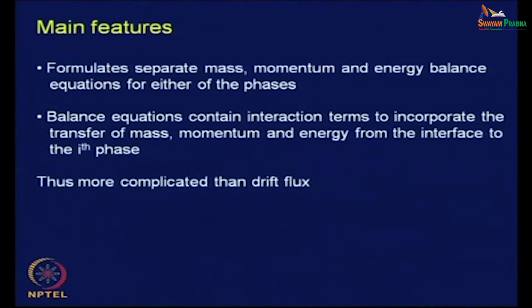Now, remember one thing: the main difference between single phase and two phase flows is the interaction terms. All these balance equations must contain the interaction terms, which incorporate the transfer of mass, momentum and energy from the interface to the ith phase. This is something very important that we must consider. If we do not consider the interaction terms, then naturally this simply becomes the single phase flow equations.